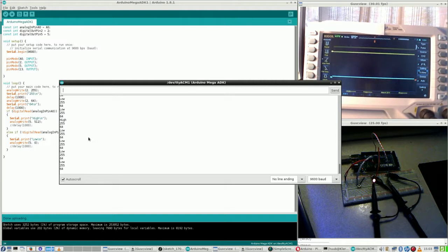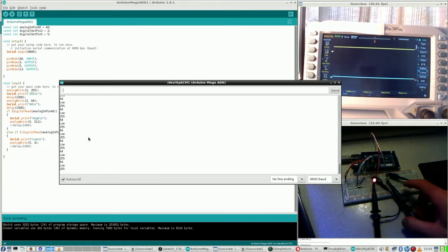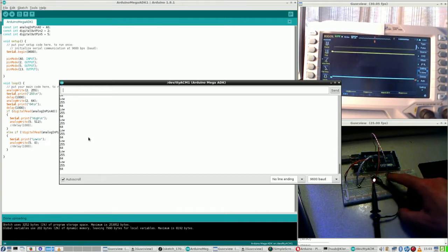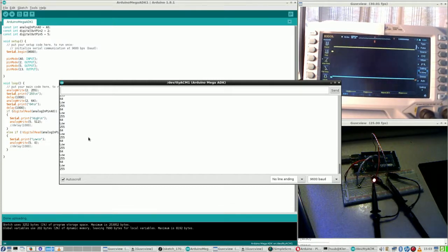This is really odd. It shows absolutely nothing. Another thing I could do is some measurement, because it doesn't even show whether there is some voltage on it. Let me do a voltage check. Always good to do.